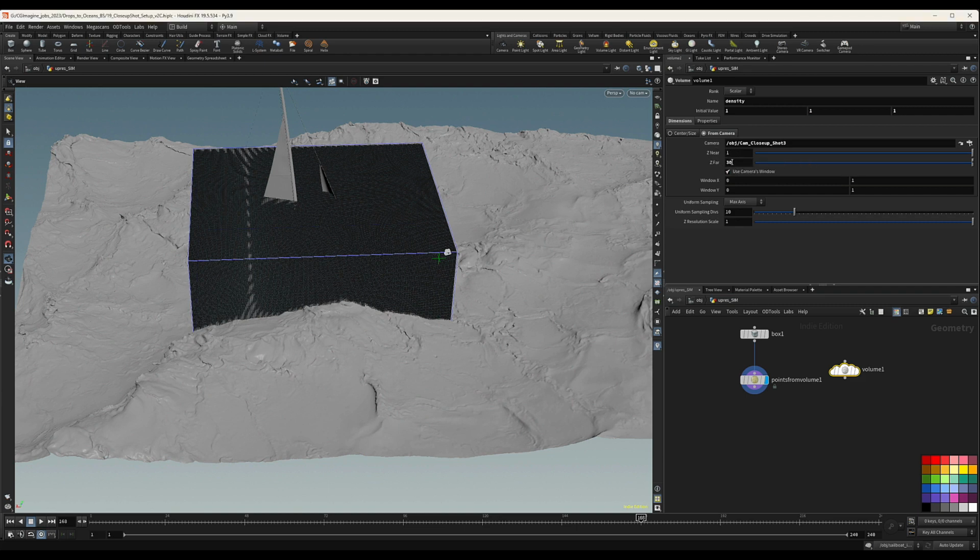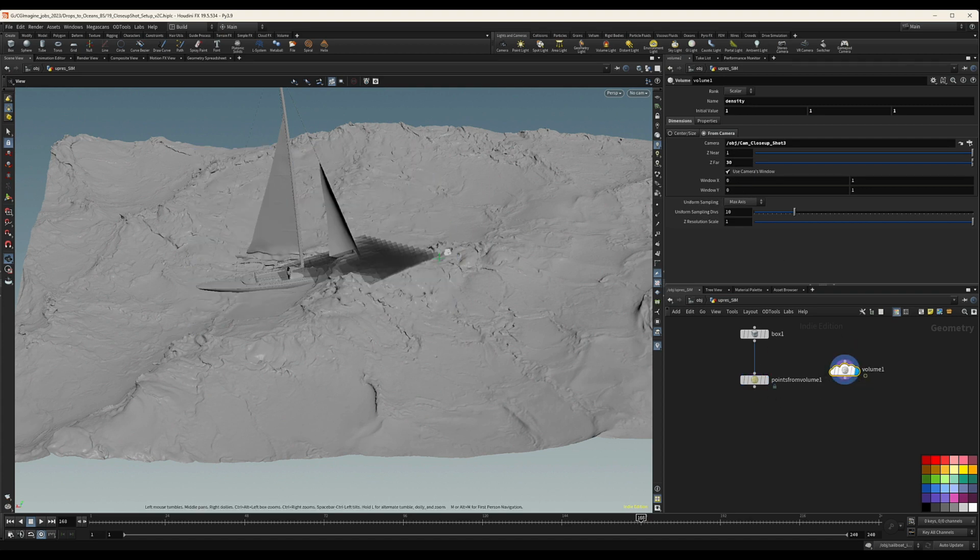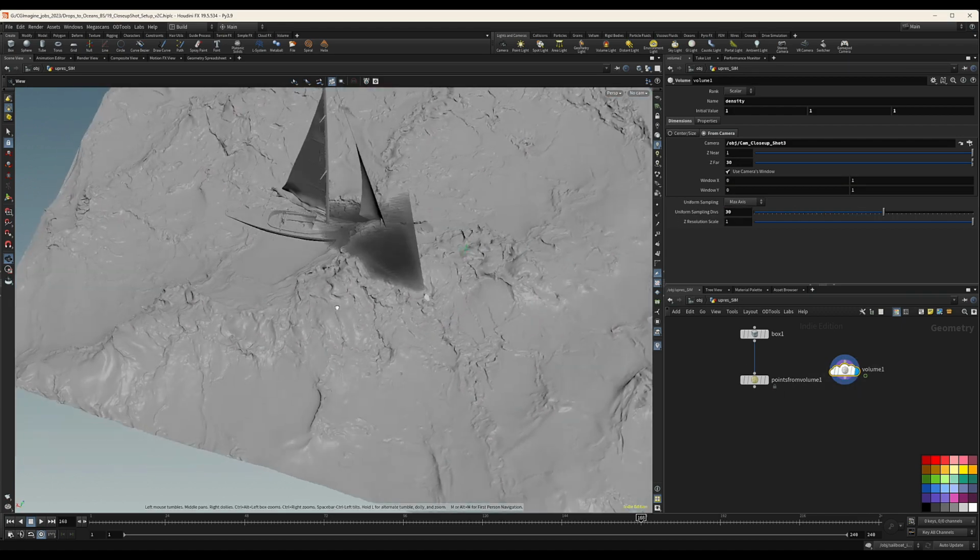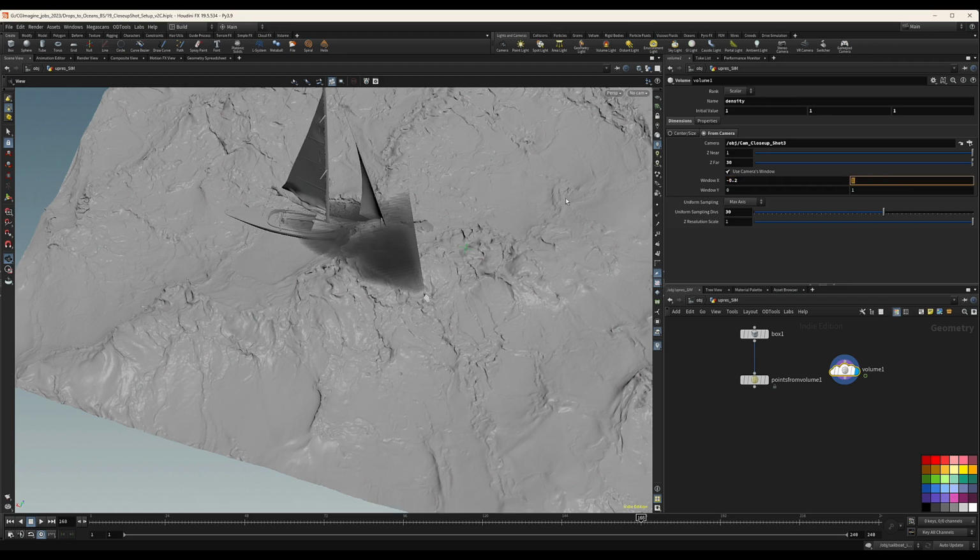So I'm going to get just 30 meters from the camera, and I'm going to increase this a little bit, like here's the bound. I'm going to also increase the resolution so we can see. This is the camera perspective, so this is the area that the camera is covering. I want to increase that a little bit, so I'm going to do minus 0.2 here, 1.2, so it's increasing, and then in here minus 0.2, and here 1.2. Okay, so now we have a little bit of room. We don't want to kill exactly where the camera stops, we need at least a little bit more room.